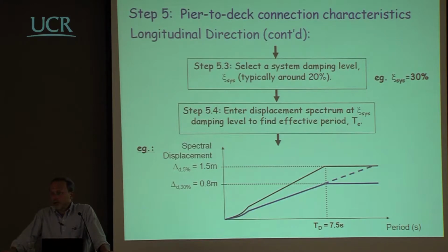Of course, you could also have connectors that do not dissipate energy, but it will be not an intelligent way of facing this problem, because if you are going to dissipate energy there, you are reducing the relative displacement, and therefore your structure will be a more efficient structure than if you use something where you don't have any energy dissipation.